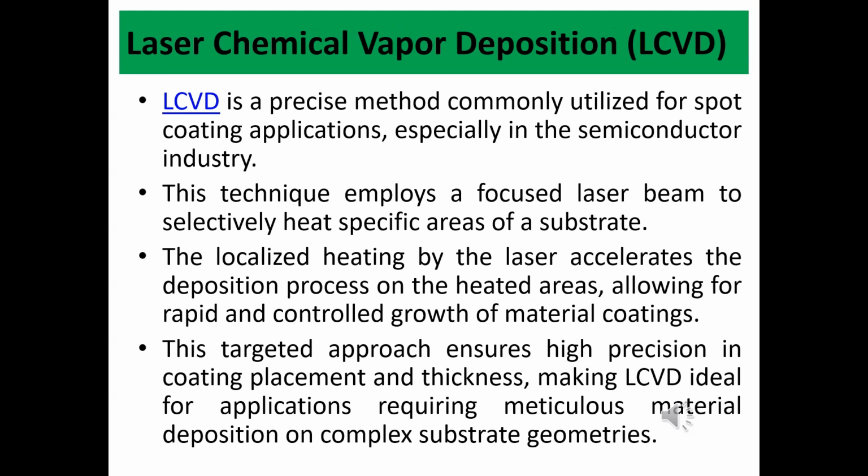Another type is laser chemical vapor deposition, LCVD. LCVD is a precise method commonly utilized for spot coating applications, especially in the semiconductor industry. So LCVD is a technique which is most commonly used in semiconductor industry. This technique employs a focused laser beam to selectively heat specific areas of a substrate.